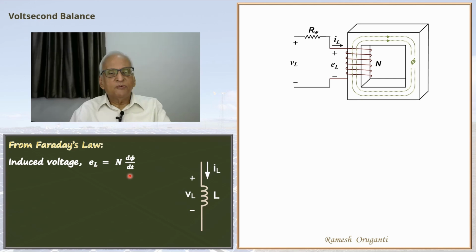So this is true whether the core is linear or not. Even taking into account the nonlinearities in the core, hysteresis, core saturation, still this Faraday's law, EL is equal to N d phi by dt, that will be valid.